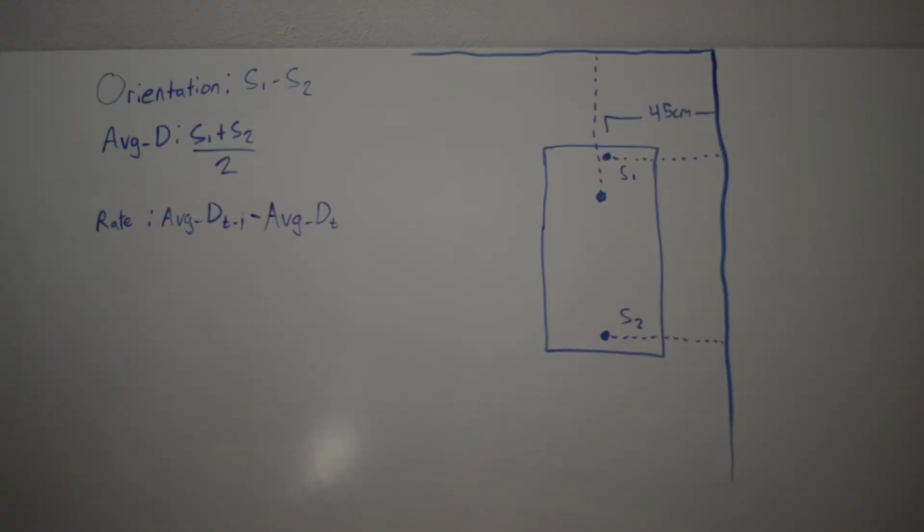Once the position of the rover is uniquely determined, the algorithm tells the rover to continue wall following until it reaches the closest corner to the end destination. Once at that location, the algorithm tells the rover to simply rotate right forever to signify that it is done.